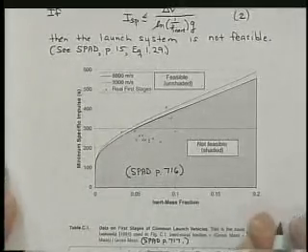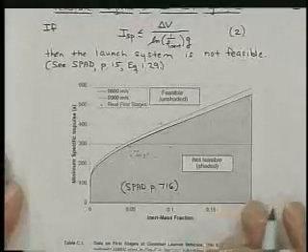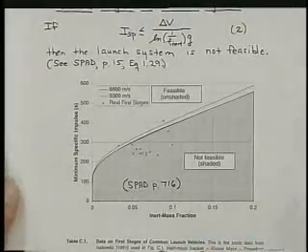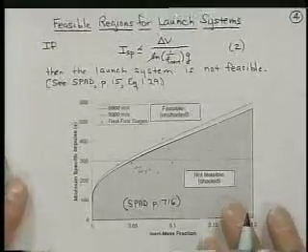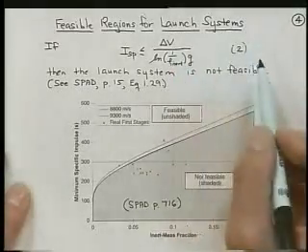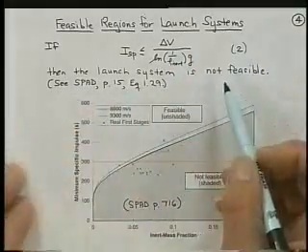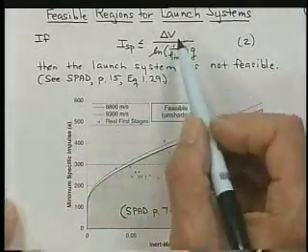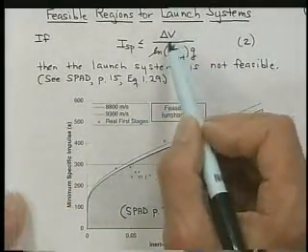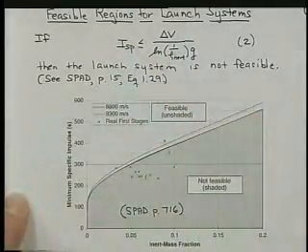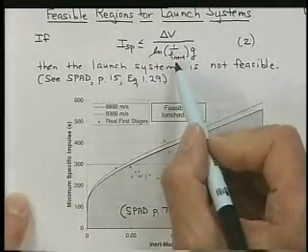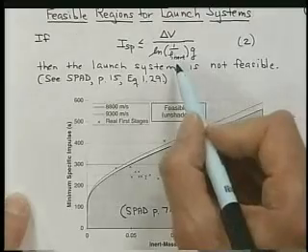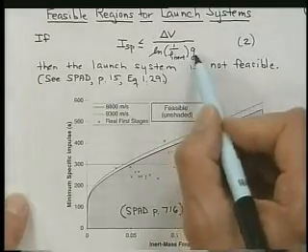So now let's look again at the feasible regions for launch systems. For a given delta V that you need to achieve, using equation 2 from the SPAD book on page 15, which is equation 1.29. If you give us a value of your delta V that you need, the ISP that your vehicle can perform, and the inert mass ratio, and G, of course, is standard free fall.